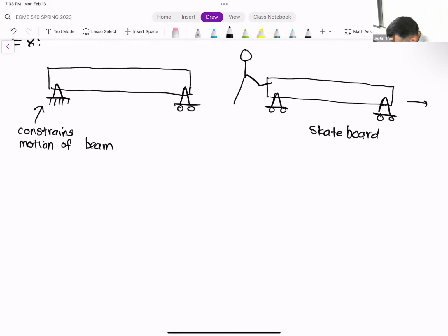I'll leave a quick note here because I know people have asked about other types of FEA. This class naturally has a lean towards structural dynamics. But if you want to do an FEA simulation on thermal heat transfer analysis or fluids, the rules are kind of the same. It's just what we define as a constraint type boundary condition that is different.